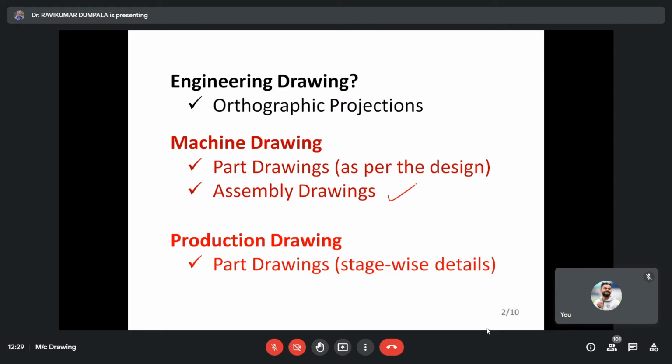As a production planner, you should know when to go for heat treatment, because the moment you do heat treatment, it puts a lot of limitations on the manufacturing processes you can use. Once you enhance the hardness to 45 HRC or 50 HRC, you cannot use drilling processes and the like. The maximum you can do is hard turning and grinding operations. These are the things you should know to make the production drawing, because heat treatment also comes in the production drawing. You have to mention at what stage you have to do the heat treatment.